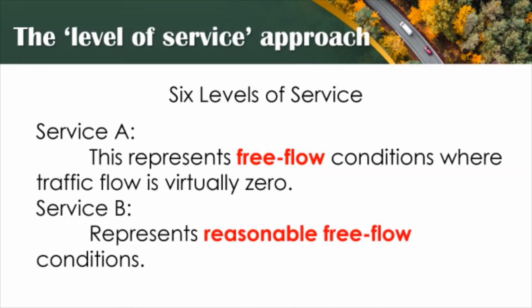Service B represents reasonable free flow conditions. Comfort and convenience levels for road users are still relatively high as vehicles have only slightly reduced freedom to maneuver. Minor accidents are accommodated with ease, although local deterioration in traffic flow conditions would be more discernible than in Service A.